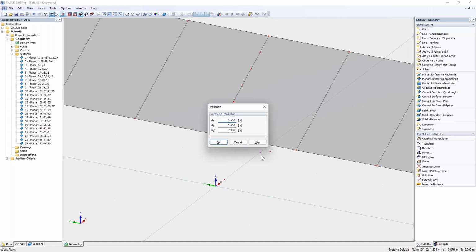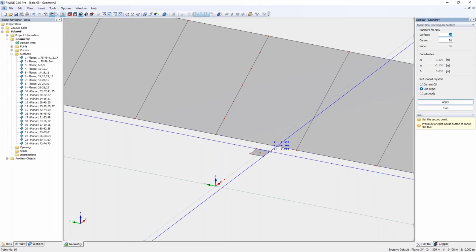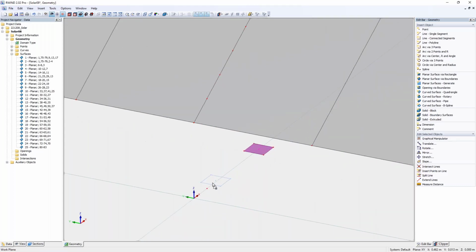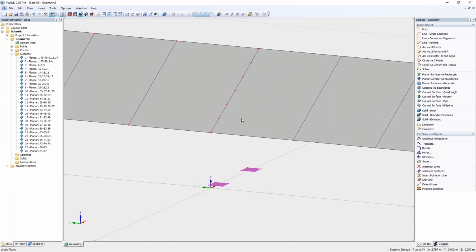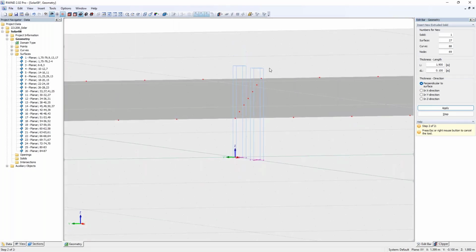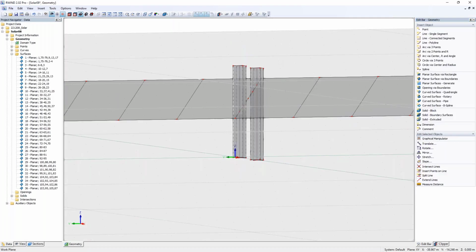So from my point of view, the quickest way to do so is to move your nodes to create the outer edge node of your rectangle, and then you can just enter it as a surface. You can, known to RFEM 6, just mark it, hit Control, pick the node in the middle and move it to the left. And now we want, of course, to have the intersection to the top, which is then curved or angled. And I will use my surfaces and extrude them. So it's up to you to just extrude them a bit higher than the current surfaces are.